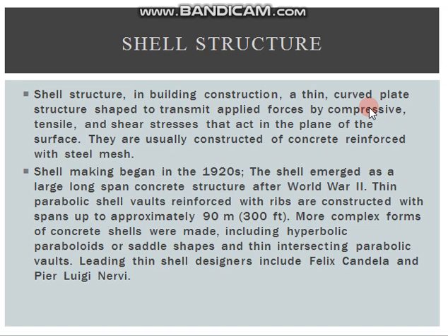A shell structure in building construction is a thin curved plate structure shaped to transmit applied forces by compressive, tensile, and shear stresses that act in the plane of the surface. They are usually constructed of concrete reinforced with steel mesh. Shell building began in the 1920s. The shell emerged as a large long-span concrete structure after World War II.